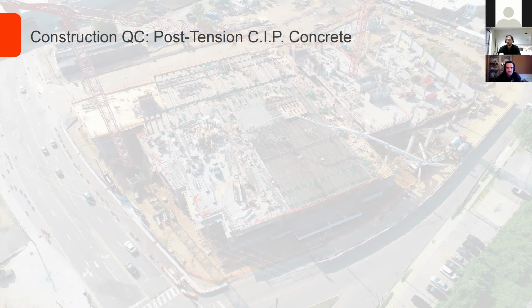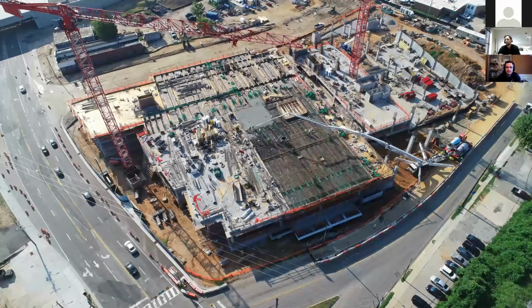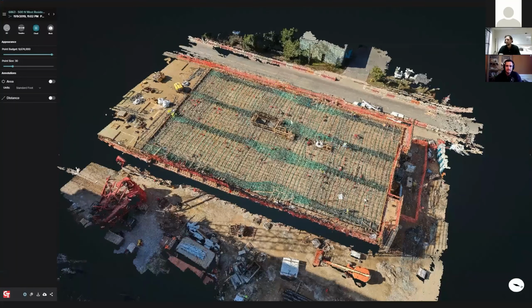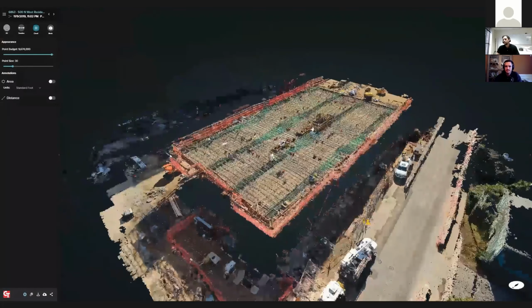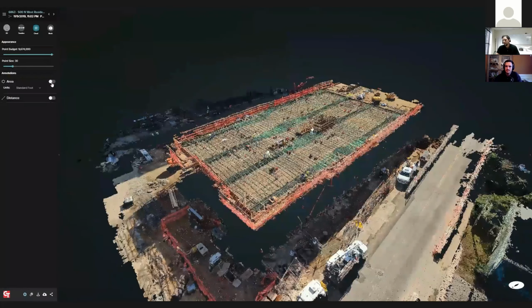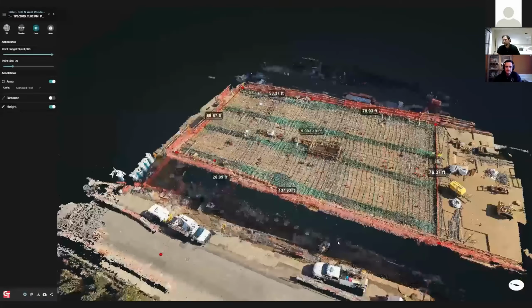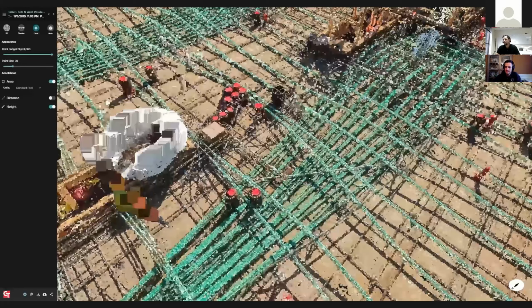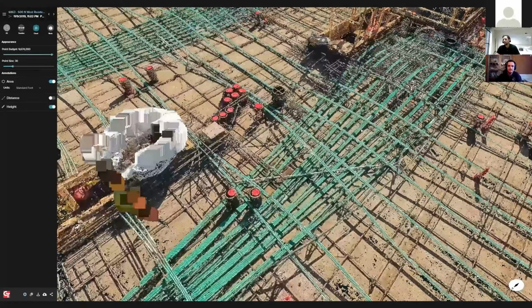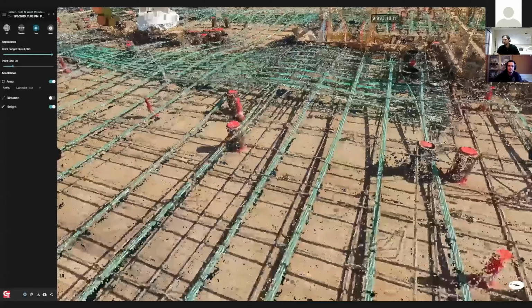Yeah. So in the manual section, I touched on doing some of the sleeve overlays. And here, I'm going to give you an example of what else we can do if we start using automated mapping. So here's the photogrammetry 3D point cloud of a pre-pour condition. The nice thing about it is the one-to-one scale. If you start using ground control and really tying it to survey, you could rely on some of the dimensions a little bit more. But it's not too bad for just photos.